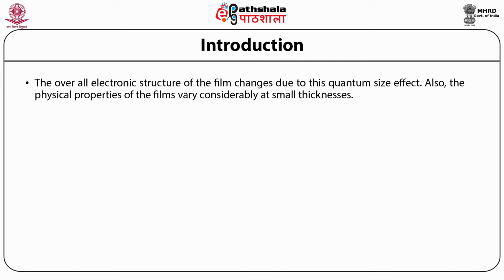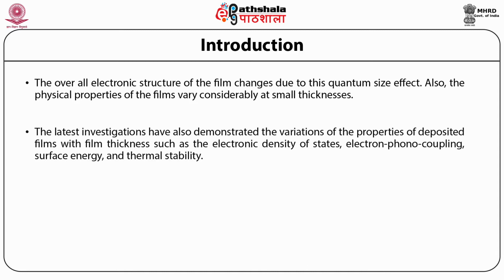Also, the physical properties of the films vary considerably at small thicknesses. The latest investigations have also demonstrated variations of the properties of deposited films with film thickness, such as the electronic density of states, electron-phonon coupling, surface energy, and thermal stability.